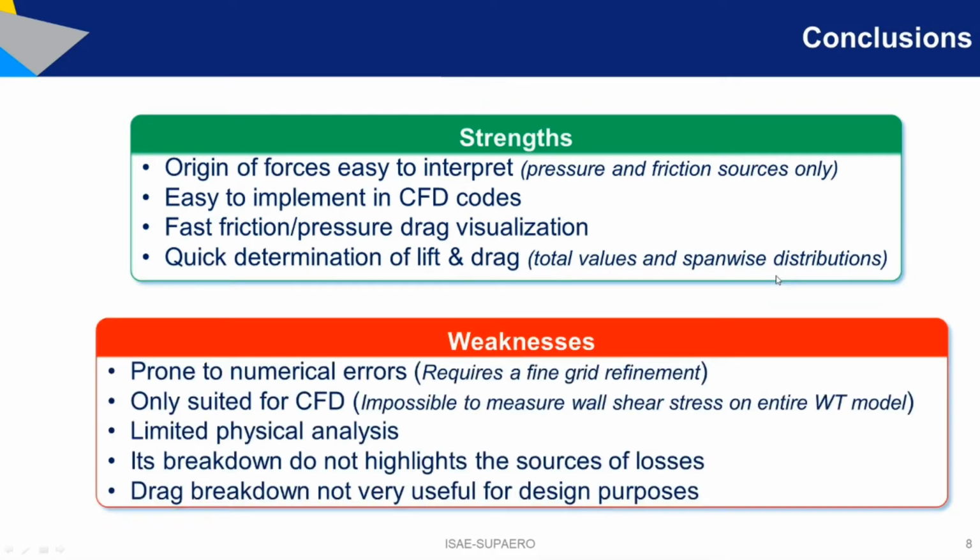But what are the drawbacks? Well, there are several drawbacks with this method. First of all, this approach is quite prone to numerical errors. It requires a fine grid, especially around the leading edge, because the method is based on the force acting at each surface, and the surface element is defined by its normal.